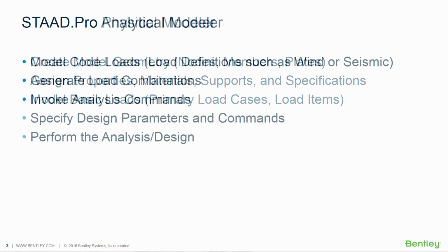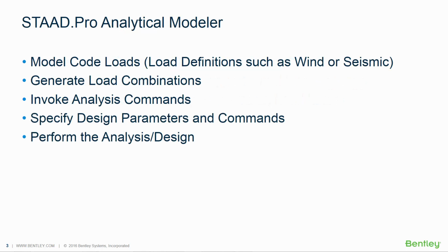After you create all of your model information in the physical modeler, you're going to move back over to the STAAD.Pro Analytical Modeler. The analytical model is a finite element model of the structure, which is typically processed directly by the analysis and design engine. There are several tasks that you're still going to need to add to your model in the analytical modeler before performing an analysis design, even if you're using the physical modeler in your workflow.